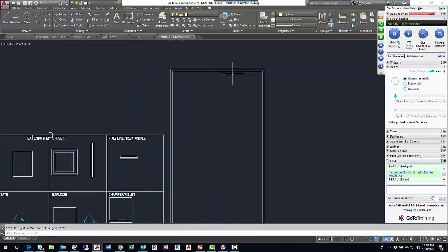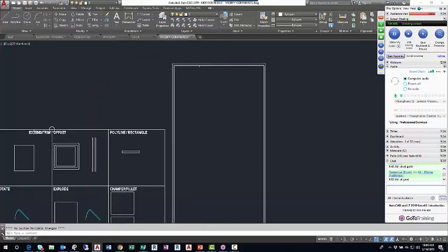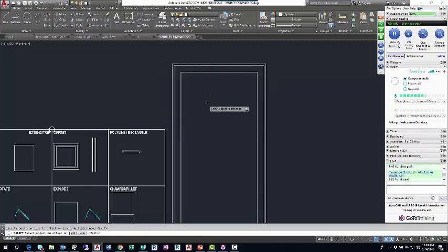But when I use the offset command, I get more rectangles, right? Just as an example, I'll go offset, 1'6", enter. I'll left click this vertical line, move right and left click. And that line, if you recall from our trim exercise yesterday, I can't trim with this. There's no cutting edge, there's no touching of lines.